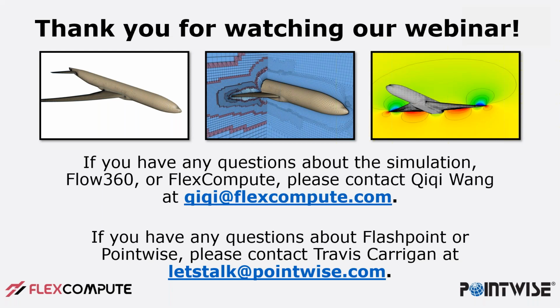There's a mapped subdivision ratio parameter in the advanced tab that's automatically set up to detect thin rectangular surfaces, and they have to satisfy certain requirements, meaning they have to consist of 4 edges that have a low, high kind of orientation to them. And then that allows us to automatically detect and apply a structured domain that's balanced properly. In addition to that, the curves have to be kind of the same length so that we're not skewing the cells or coming up with completely different distributions on opposing ends, kind of the same requirements that you would have for any structured mesh that you're creating.